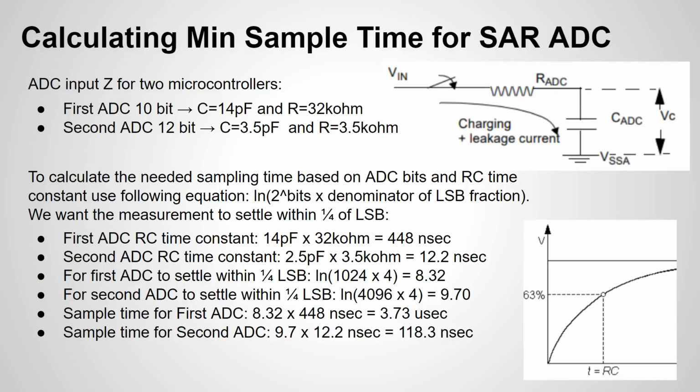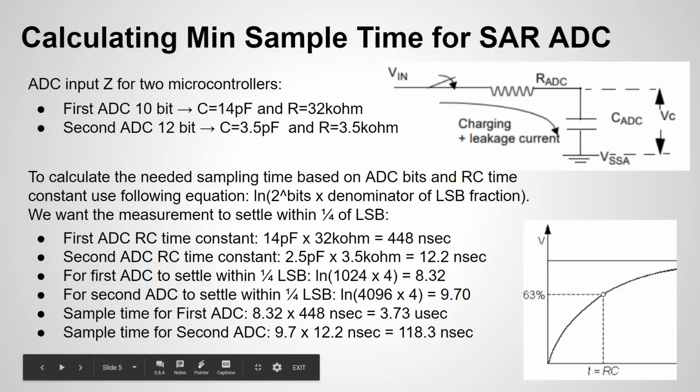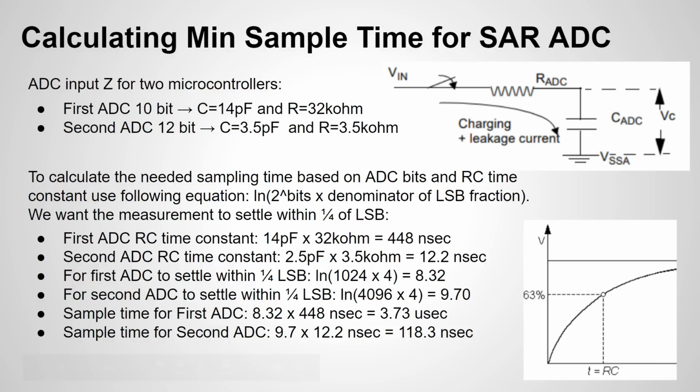And remember, it's going to be highly dependent on this RC time constant, which, because of the value of R and C, basically determines the time to charge up the cap. And remember, an RC time constant is not the cap fully charged, it's the time it takes the cap to get to certain points in its charging cycle, and one RC time constant is 63%, and you can see this is a non-linear curve. Once again, I'm assuming you've seen this before or have some background on RC time constant. If not, just look up a tutorial on capacitors.